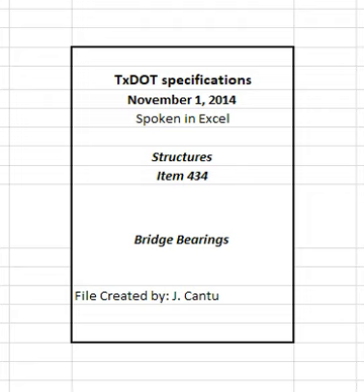Presence of chlorinated compounds, neoprene, in the elastomer will be verified by the department in accordance with TX 601J, Part 4 Chlorinated Compound Test Method. Costs associated with testing elastomer formulations failing to conform to the requirements of this item are borne by the bearings manufacturer. This cost will be assessed at the rate established by Construction Division at the time of testing.